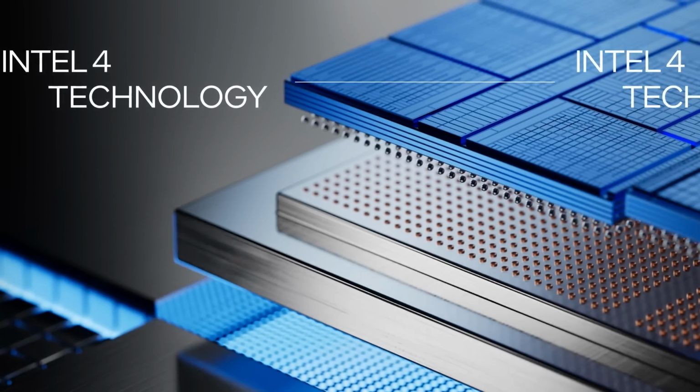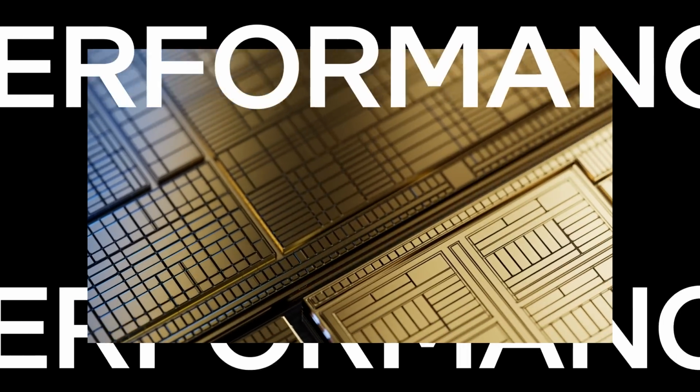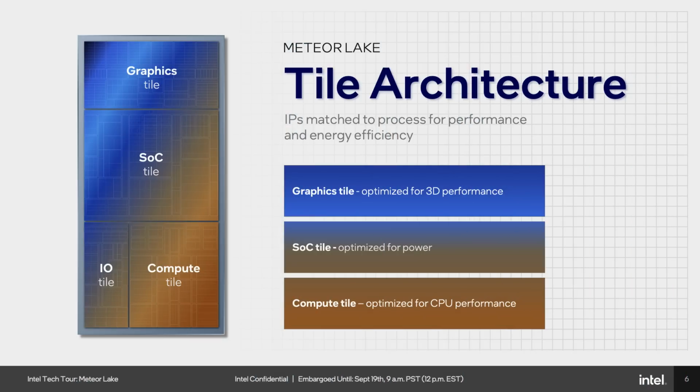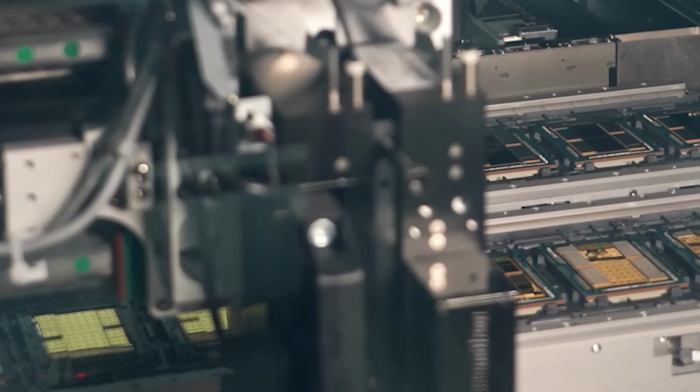I'm your host, Alejandro Hoyos, and I am very excited as we're going to be talking about Intel's latest processor, Meteor Lake. We have gone from a monolithic die to a complete disaggregated multi-tile, which is Meteor Lake. We're going to be interviewing different architects and engineers that are going to take us through different tiles of Meteor Lake, which are the I/O tile, graphics tile, compute tile, and the SoC tile. We also had the opportunity to travel all the way to Malaysia to learn more about Meteor Lake's packaging and tour the different facilities that cover assembly and testing.